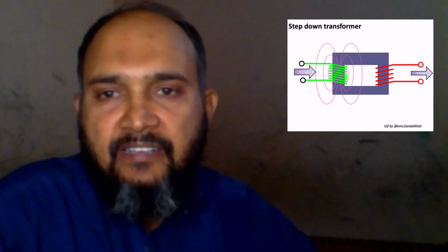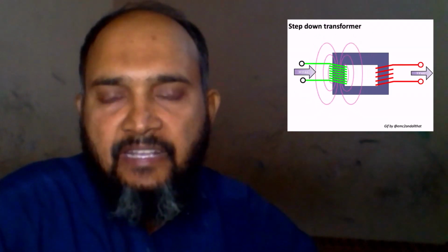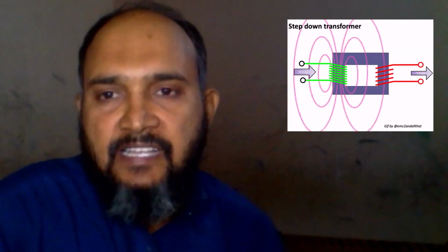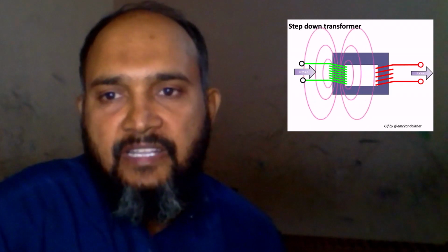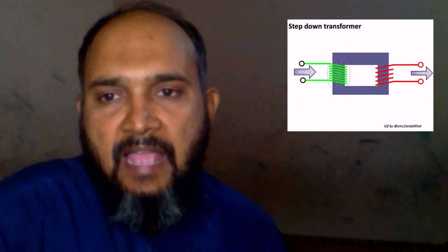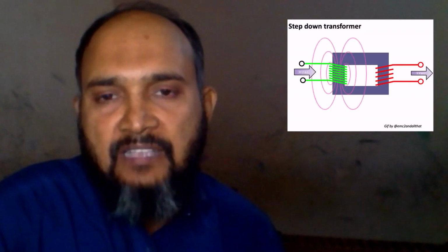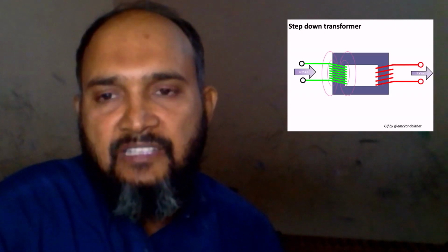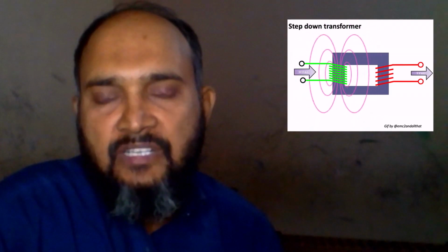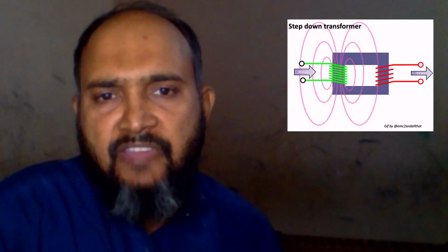DC stands for direct current, meaning voltage or current that maintains constant polarity or direction, respectively, over time. AC stands for alternating current, meaning voltage or current that changes polarity or direction, respectively, over time. AC electromechanical generators, known as alternators, are of simpler construction than DC electromechanical generators. AC and DC motor design follows the respective generator design principles very closely.